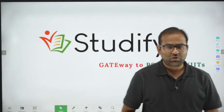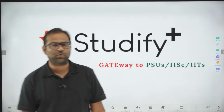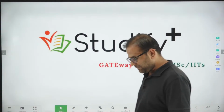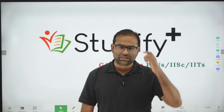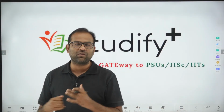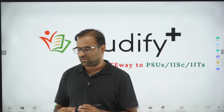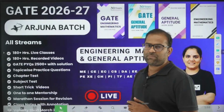So welcome to the Studify Plus, our next session on the last two port parameter, and that parameter is known as ABCD parameter. Why is the ABCD parameter very important? ABCD parameter, also known as transmission parameter, is useful for cascading of the system. When systems are cascaded, you can directly multiply the cascaded system using this ABCD parameter. So let's talk about our next very important two port parameter.